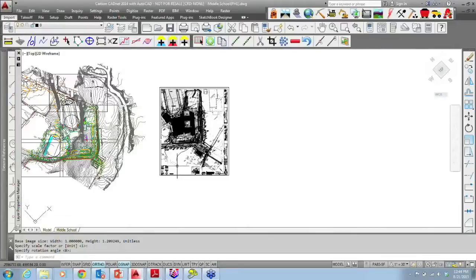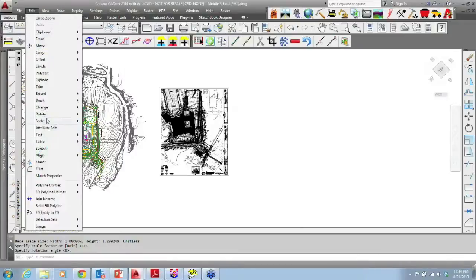Well, instead of doing what we did before, and that is scale and use the scale wizard, this time I want to use align and use the CARLSON 2D align command. This command, unlike AutoCAD align, which is below it, only works in 2D, northing and easting, and even if you pick something that has a Z, it will only use the northing and easting and set everything to 0. So you don't get elements or raster images that are coplanar to the axis of the XY. So at this point, I'm going to pick 2D align.